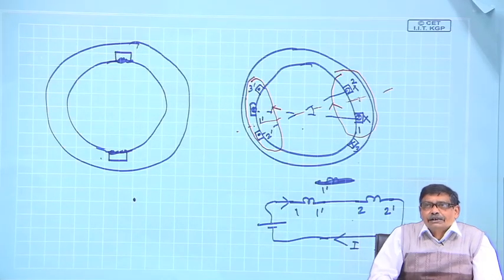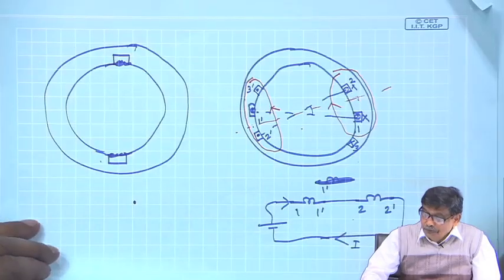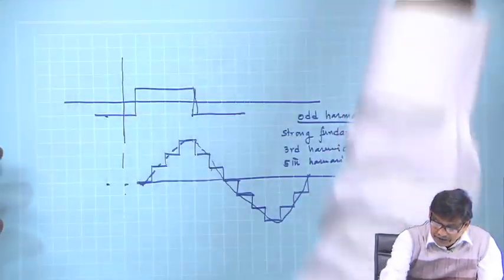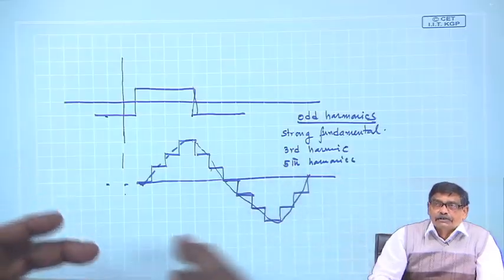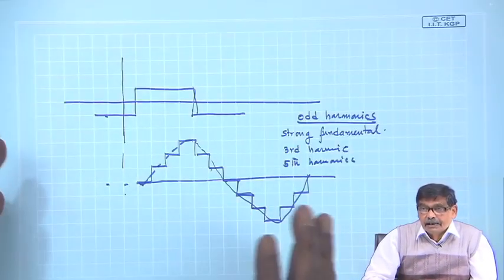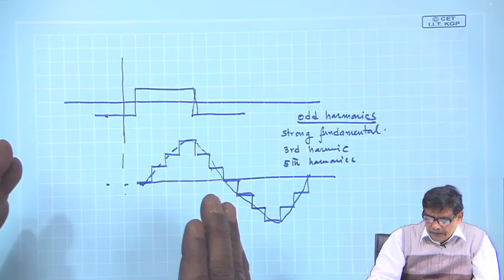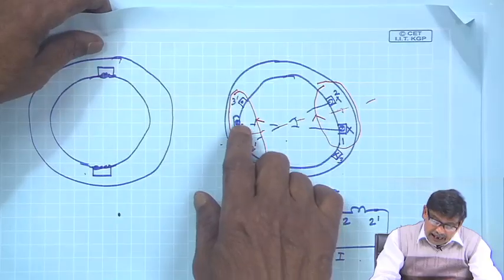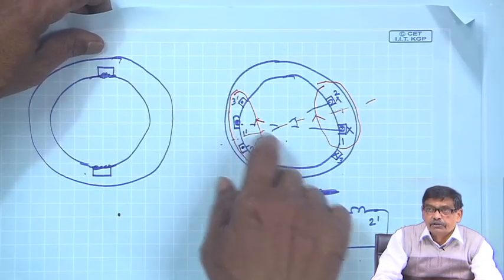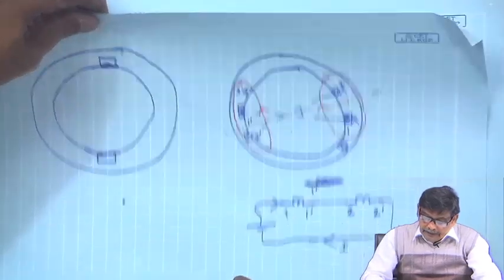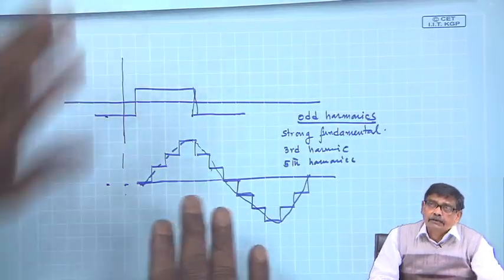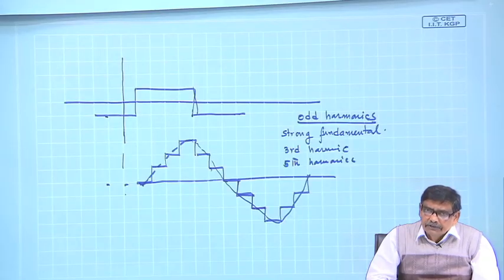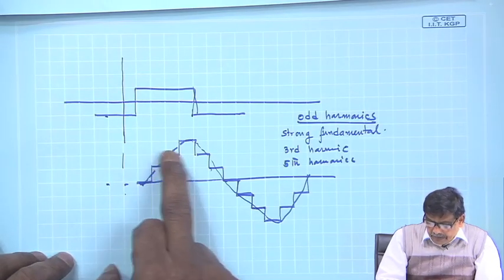we will show you that it is possible to nullify the predominant harmonics. One predominant harmonic at least can be eliminated by properly choosing the angle between two subsequent conductors of a particular group. Therefore, this is the thing that is done: do not use a single coil, use distributed coils and get a stepped B distribution.